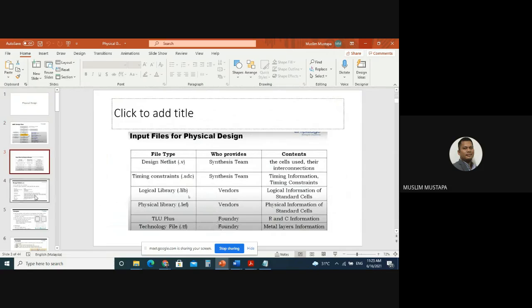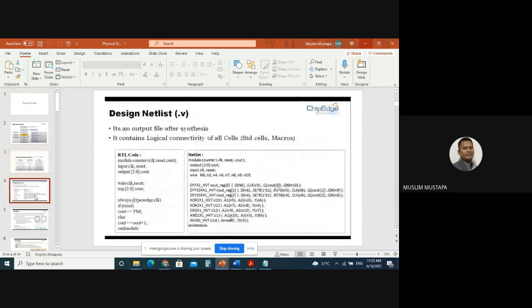This is the difference between the RTL code and converting it to a netlist. When you want to make it into circuitry on the chip, you have to change the RTL code, the hardware description language, into netlist code, so that it is more circuitry oriented, or gates oriented.